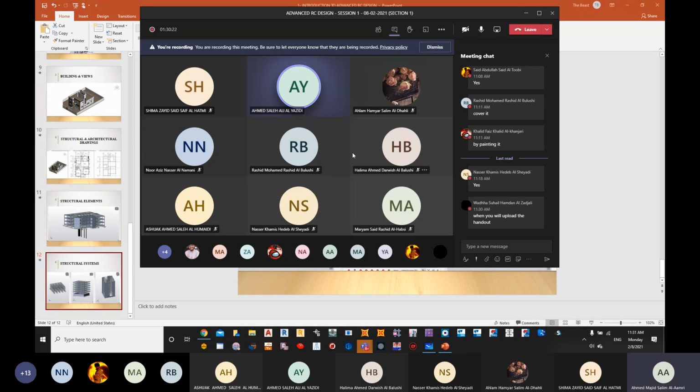No, it's not about avoiding the beams, but normally whenever you are having your flat slab system, by removing the beams, the own weight of the whole system is going to be a little bit lesser. Whenever it goes lesser, you can extend the span between columns to columns. The same thing whenever you are going to go for waffle slab. If you want longer span between column to column, you can use waffle or ribbed slab, or you can use post tension slabs. So different solutions, either by reducing the weight of the slabs.